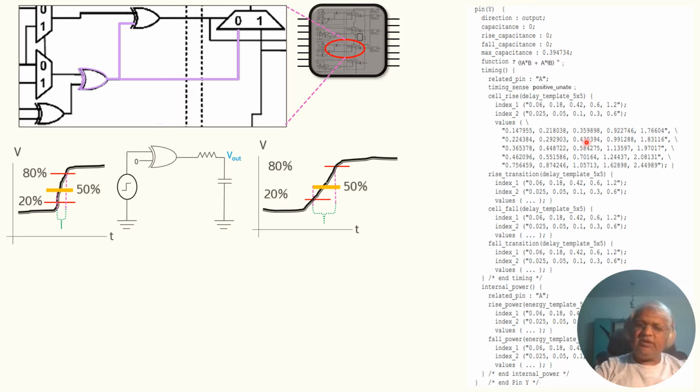Tools generally use more complicated models, such as CCS models, so you can get more details from those. They take the voltage model, and based on the voltage over time, they figure out the current, and then figure out the delay. It is a bit more complicated. For understanding purposes this is very easy, so we will take this one. So this is how the delay is calculated.